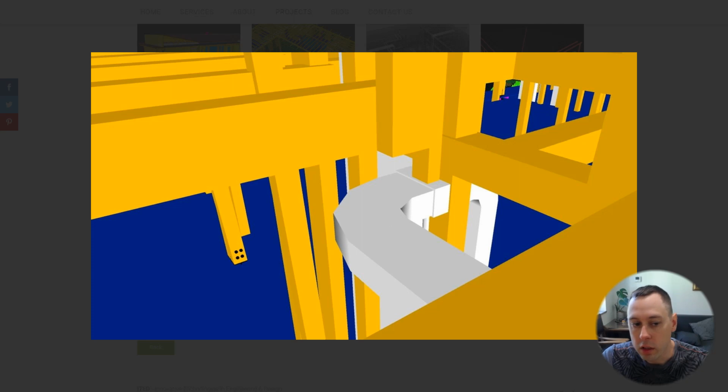After conducting the checks, you will receive a list of clashes. You typically need to go through them to identify any major issues, and then forward those issues to the designer for fixing. Typically, this method is carried out using paid tools like Autodesk Navisworks. However, there are also free-to-use tools with limited but useful clash detection functionality, such as the Open IFC Viewer, in which I will show you how to do the clash review today in this video.